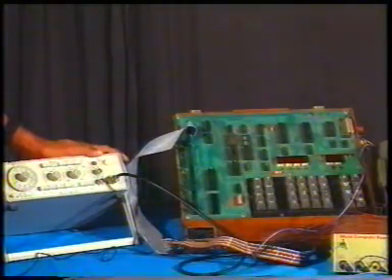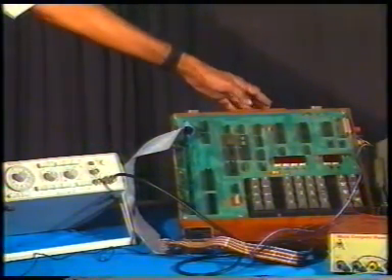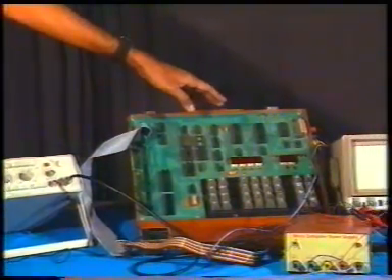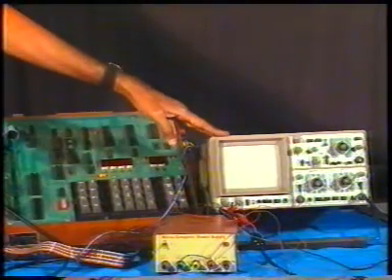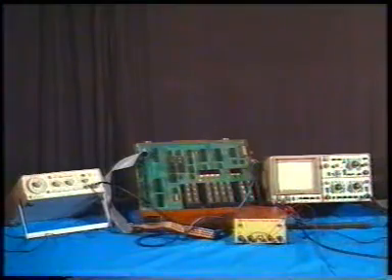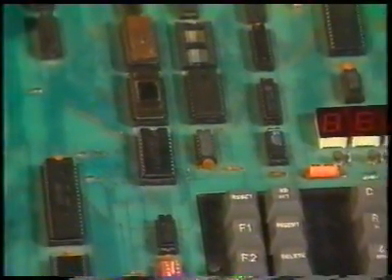Friends, we have seen the description of modes 0, 1, 2 and 3. Now we will view a demonstration which implements mode 3. The clock output of the function generator is given as the clock input to the 8253 of the microprocessor trainer kit. The output of 8253 is connected to the oscilloscope. The clock input is also connected to another channel of the oscilloscope so that clock and output of 8253 can be viewed simultaneously. The counter 2 of 8253 is set for mode 3 and BCD count.